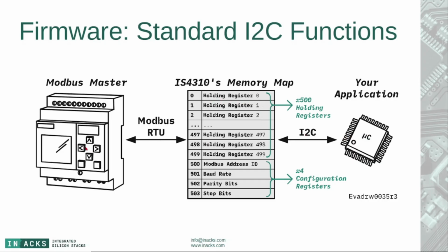So the PLC, your client, the master, your computer, to read the data of your sensor that you stored in this holding register, the Modbus Master only has to read holding register 0 and will get the value that you stored there using the Modbus communications, which are all transparent to you as you are using the IS4310.